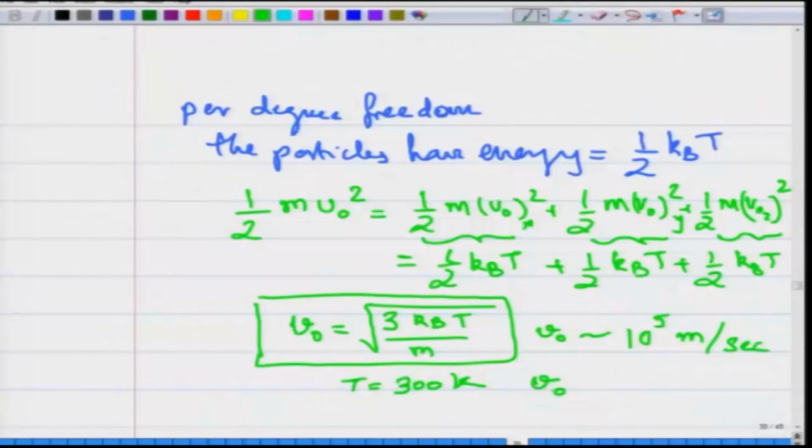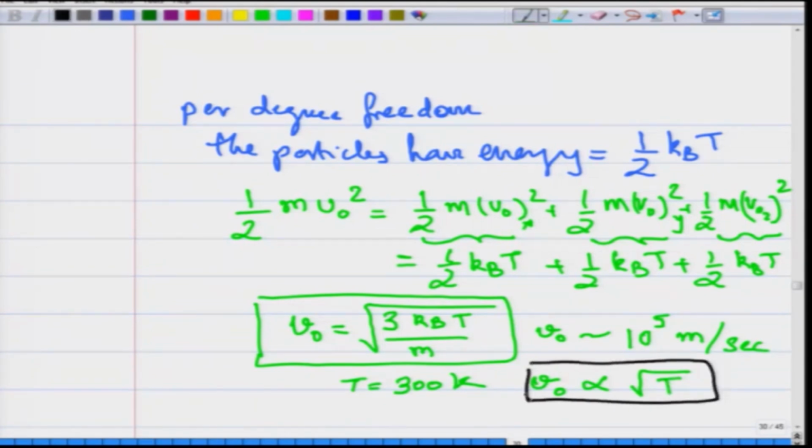So now you can estimate the velocity of electrons, and you also know the scattering time. Before we go further, Drude's model, which assumes a Maxwell-Boltzmann type distribution of energies of electrons inside the solid, shows that the velocity should actually be temperature dependent, proportional to the square root of temperature. This is one outcome of Drude's theory which you should know: the speed of the electron inside the solid changes with temperature, by the square root of the temperature.